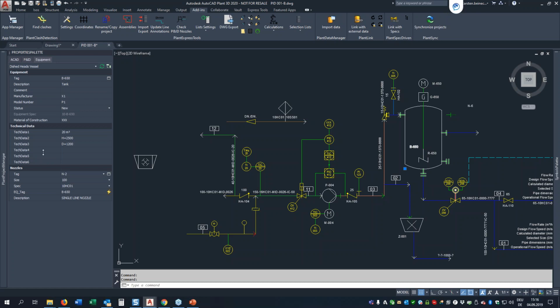In addition, you can also use the properties of related classes. And that means, for example, for equipment, I see here some general equipment properties. I see some technical data. That's also properties of the equipment. But here I have the properties of a nozzle, and it's not just one nozzle. Like in 3D, I can switch to this one here, to nozzle 1, and I can set the property, the value. So here it's not acquired anymore. So you can also edit the nozzle properties.